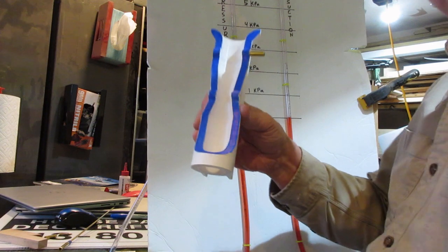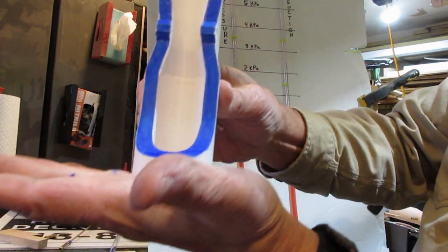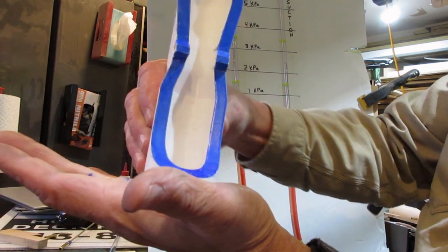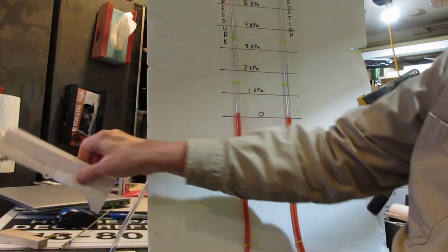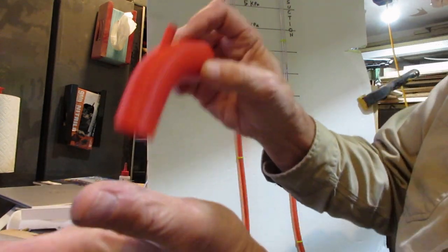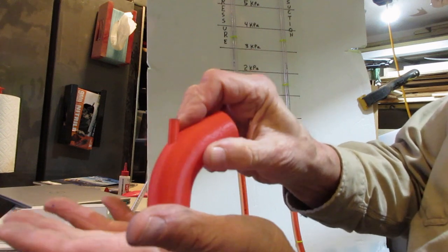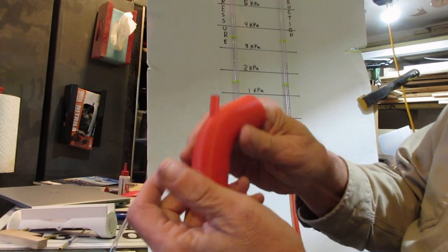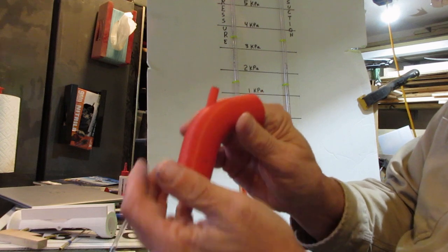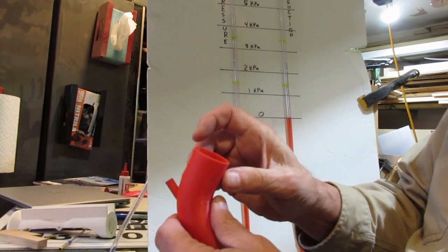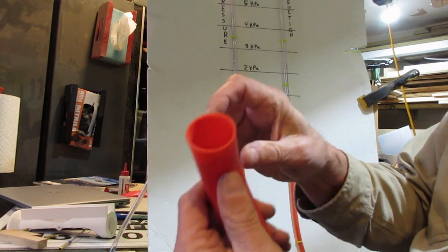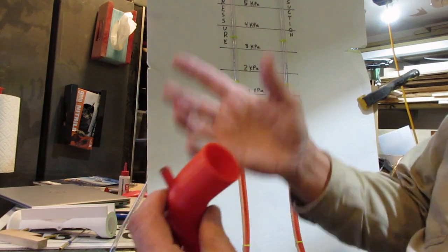Okay. These, set them on the print bed like this without supports, the cutaway and the Venturi. There's no problem. The overall height is short enough, it'll fit most printers. This one I printed this way, but I did turn on the supports using Cura slicer with the tree supports. They pop out pretty quick and clean and easy, both inside and out where it needs support. So that worked out easy to print.